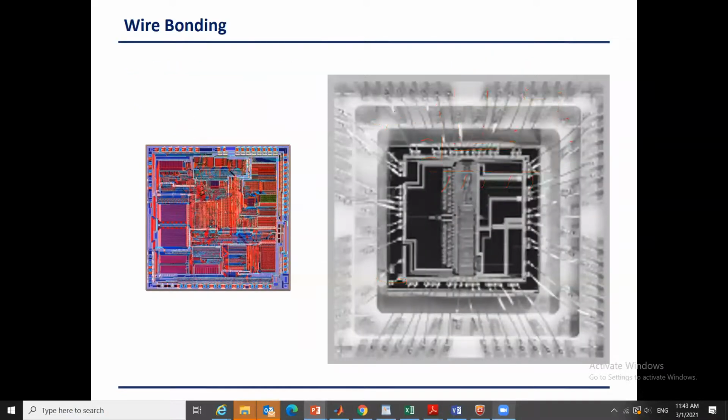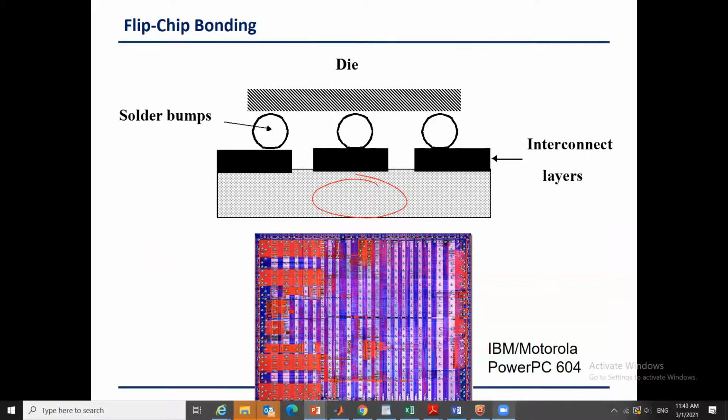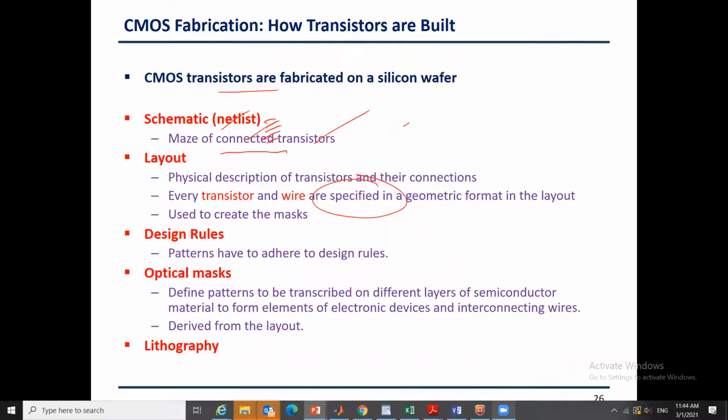So this is really an image of a chip, how it gets connected to the external pins. You see here the wiring, and then also now there is more complex stuff, as Imad said. What if I want to connect my chip to another chip? First, they started with flip chip bonding. I have two chips and I flip them on top of each other to connect the bonding externally using some soldering points. I make the last layer metal, put insulator or something between them, and then I put another die. But now we are talking about 3D chips.